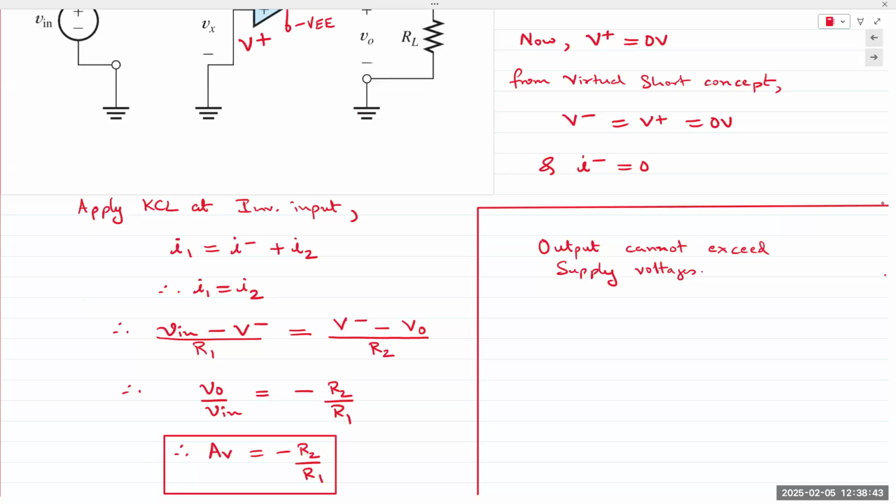So even if the AC signal, let's say you apply plus minus 10 volts. Okay, so the maximum swing would be minus 10 to plus 10. If you have a gain of 100 in your circuit and you apply 1 volt, right, 1 volt AC signal, your output is going to clip at 10 volts, plus minus 10 volts. Okay, it's going to saturate at the power supply level.